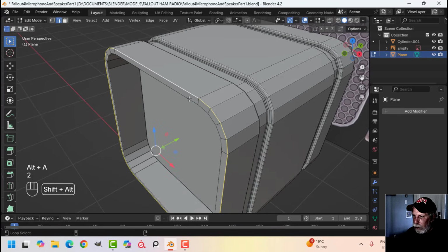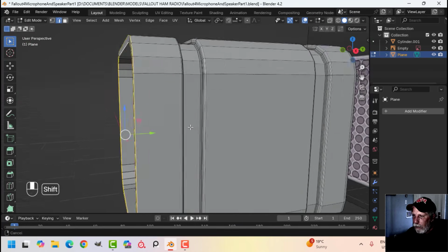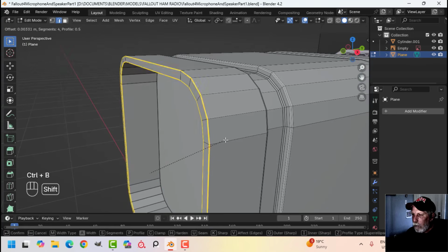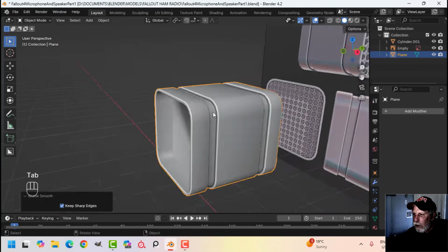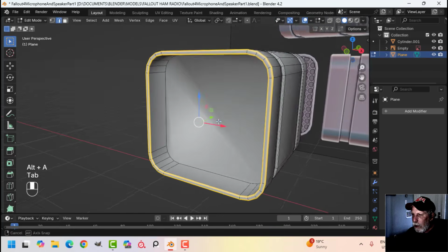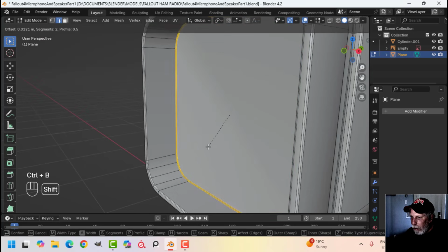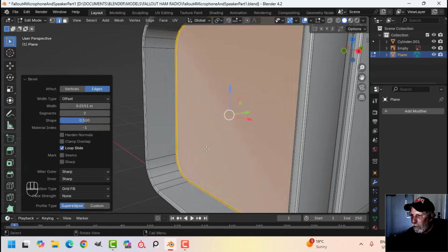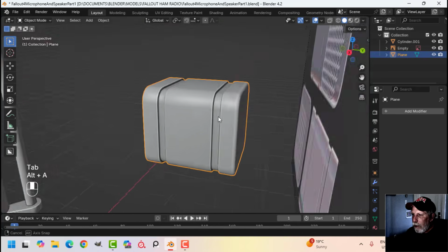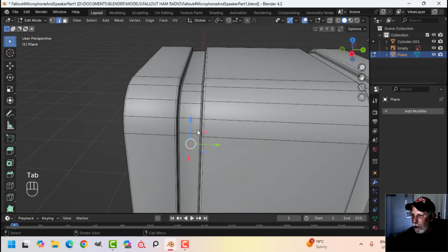And finally, we're going to select these two edges and bevel them. Control B and pull, but I just want the 3. Let's try shade smooth. Now it doesn't look right yet, so we're going to come in here, and I'm going to try, let's bevel. Shift Alt and click that edge, and Control B and pull with 3, right? Okay.